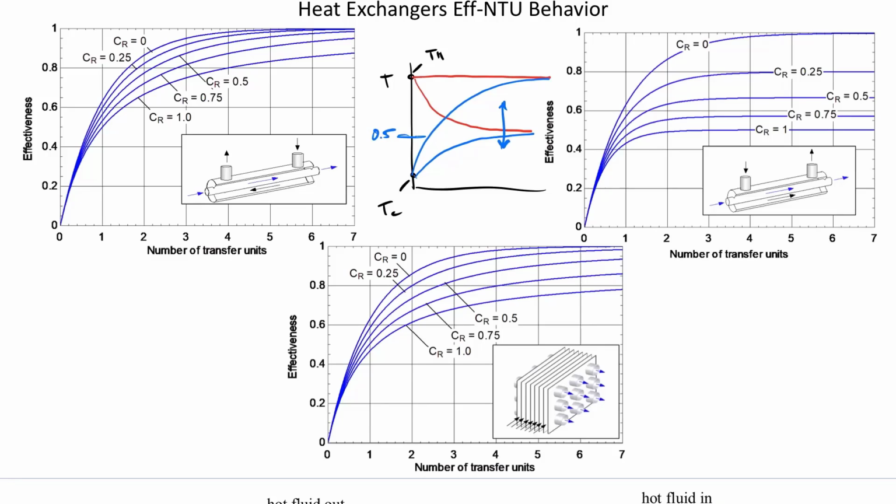One other thing to point out, last thing I'll point out. If you're designing a heat exchanger and you calculate your NTU, which you should do, you will hopefully find that your NTU is in what we call a reasonable range. So if I was designing a heat exchanger and I calculated an NTU of say 0.1, what would that tell me about my design? It'd tell me I could make my heat exchanger marginally bigger, just a little bit bigger, and get a huge gain in performance. So why wouldn't you add a little bit of extra area if you're down here? You get a lot better performance.